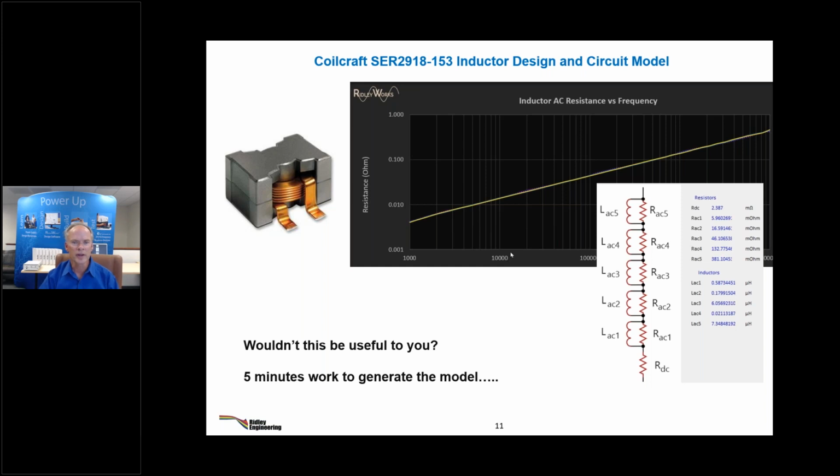All right, in the first transformer winding, we split the primary winding. So we did half the primary, then a secondary, then the other half the primary. What that does is it reduces the field strengths. So instead of going through 2 layers and get a field strength of 2, I only go through 1 layer, and then the field strength hitting the secondary is a strength of 1.